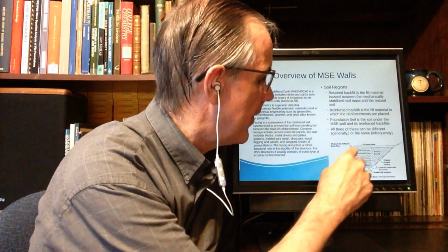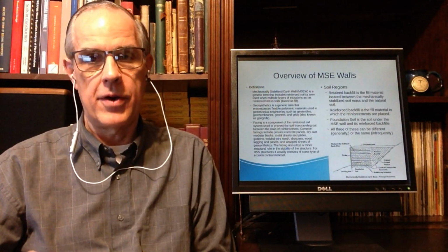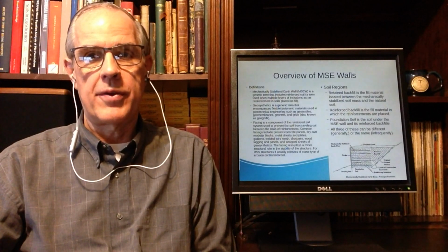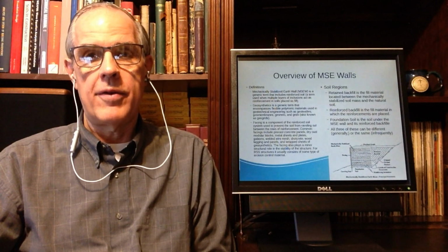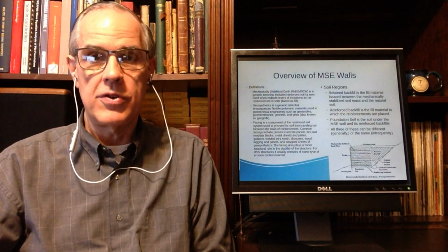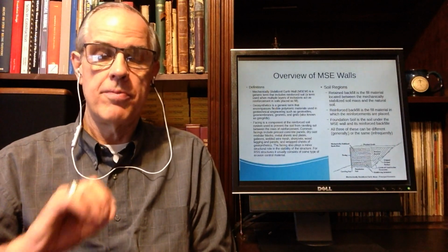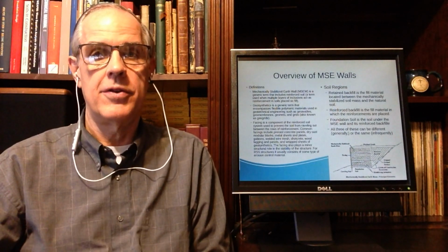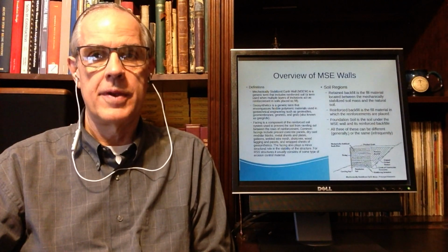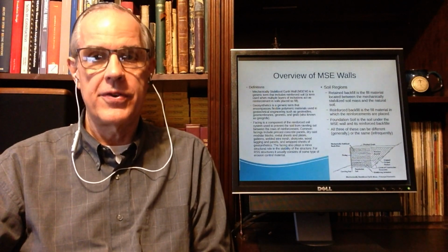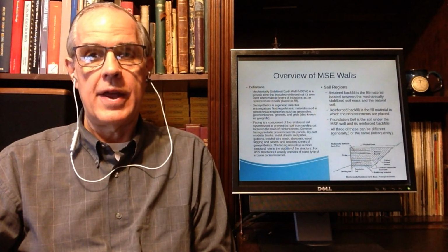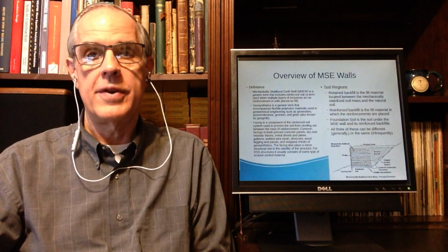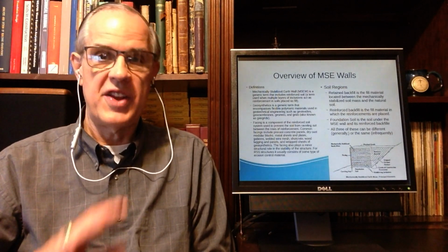Or reinforced backfill. All MSE walls are backfilled from the get-go. You do not have a situation like with concrete gravity walls or later with sheet pile walls where you have the option in some situations to use the existing soil. With MSE walls, you basically have to write your own ticket, so to speak, on the backfill. And that's an advantage. That ensures that you have a nice, free-draining, cohesionless backfill, which, as I explained before, is a key to success with any retaining wall. But with MSE walls, it's mandatory.